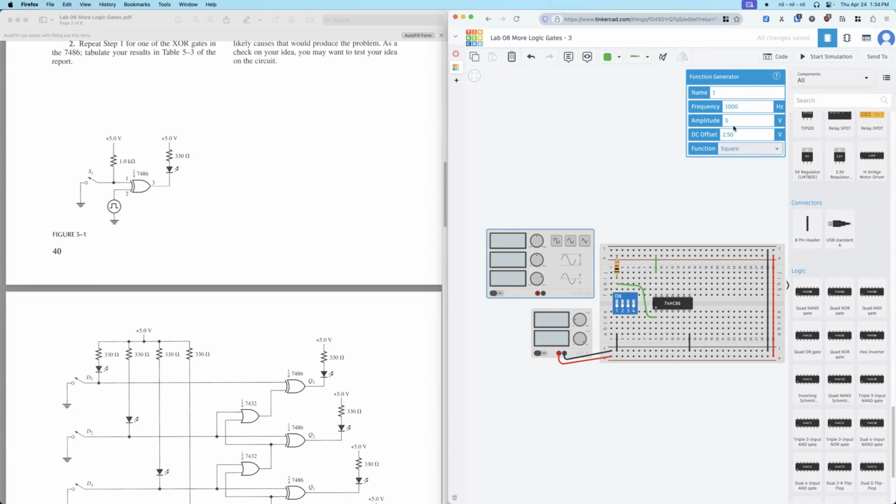So this is the one we need. Okay. Then negative, just connect to the ground. Then positive, we need to go to pin 2. Okay, so this is pin 2.